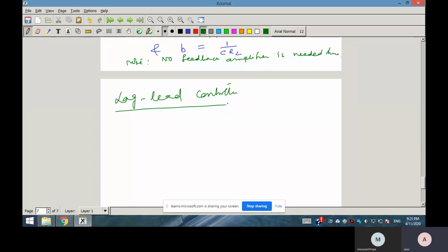So using a lead compensator, we saw that the system will become very fast. Gain crossover frequency will increase because it will provide phase lead as well as gain amplification. In case of a lag compensator, phase margin can be met by providing gain attenuation. So using a lead compensator the system will become very fast, and using a lag compensator the system will become very slow.